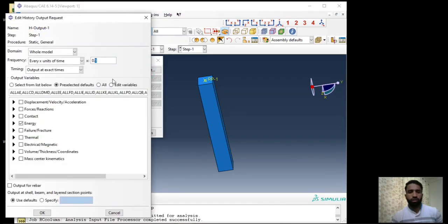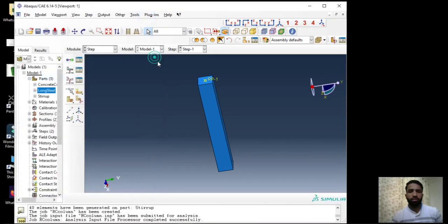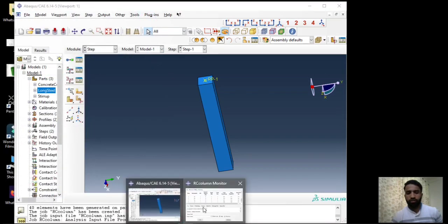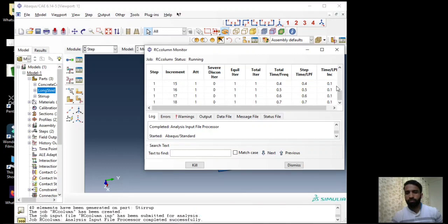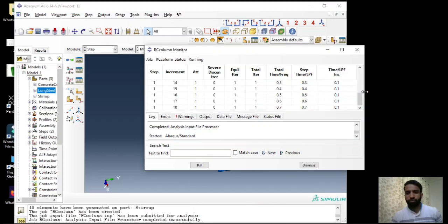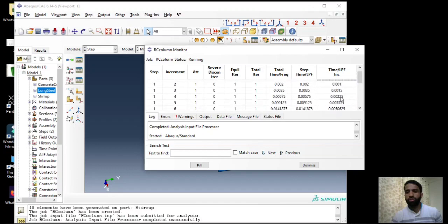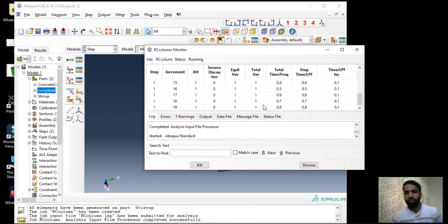We are all okay. It is in the steps that the increment that we had used has really created this problem. Because initially we wanted to use 0.001, it won't be going to 100. It will finish soon. 0.1 is what we had asked, but since we had already given an initial time increment of this, that's why it has taken a bit more number of frames.